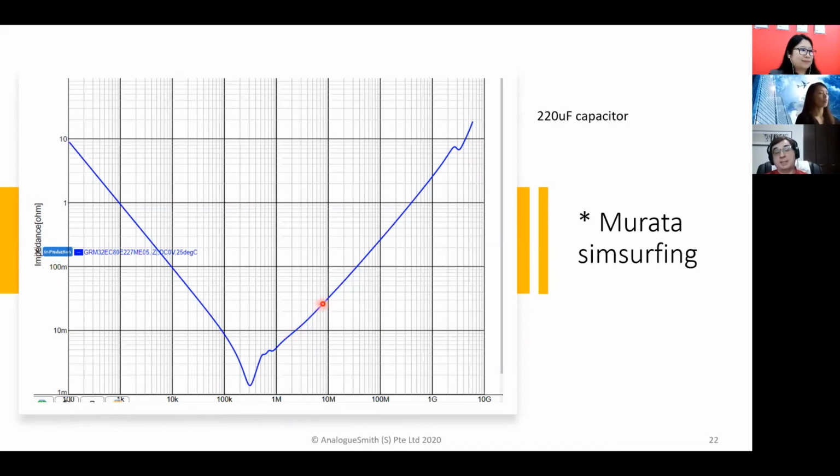Now, a capacitor's impedance decreases with frequency, an inductor's increases with frequency. So we no longer have a capacitor here. We're increasing impedance with frequency. That means we have an inductor. So on one side of this drop, and this is what's called self-resonance, we have a capacitor, which is what we're paying for. And on the other side, we have an inductor.